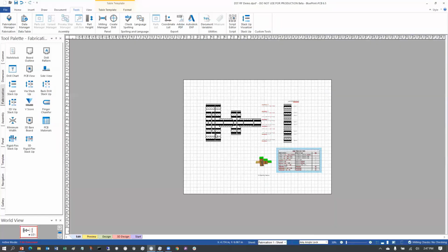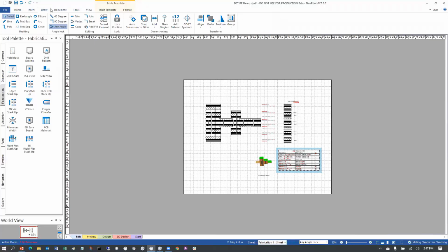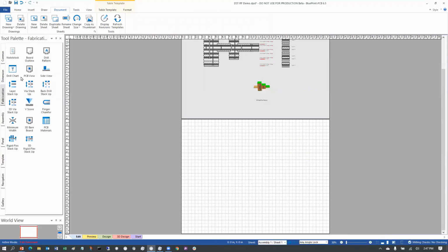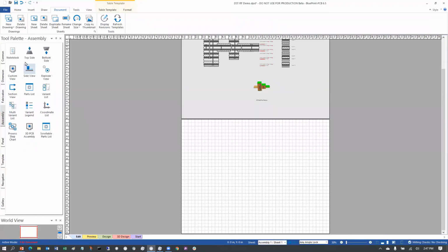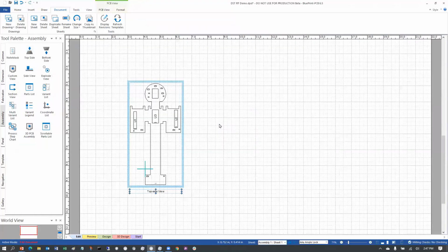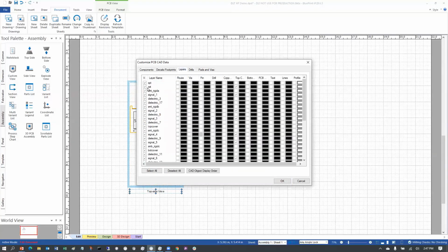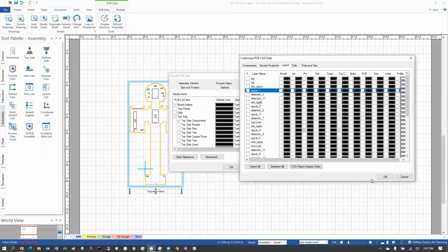And then finally, if I go to assembly drawing now, I'm going to add an assembly drawing. And I'm going to put down a topside view for an assembly drawing. Now, this is the fully assembled built board with all of its board outline, not its layer profiles. But again, I can go in and say, okay, I want to show a layout of just the top layer, right? So I select all these layers. Now I want to show only the signal layer. I'm going to sort of step through this as I go.